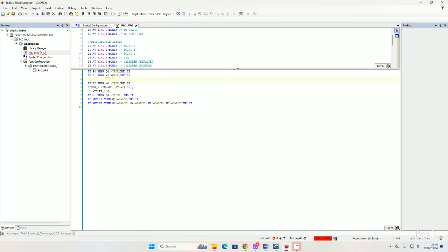And then this memory latch, we're now going to give it a timer. So instead of our timer being timer_1, now it's going to be timer_2, because it's a second timer. You're introducing another timer, you are not using the same timer. And then your memory, it's still going to be 2 because that's your input, right? And then your processing time, how long do you want to delay? You want to delay by 5 seconds. So T#5s, close, don't forget a semicolon.